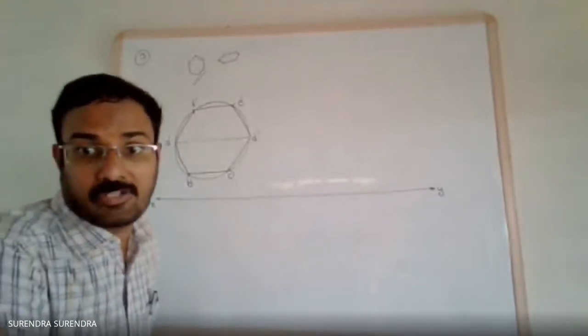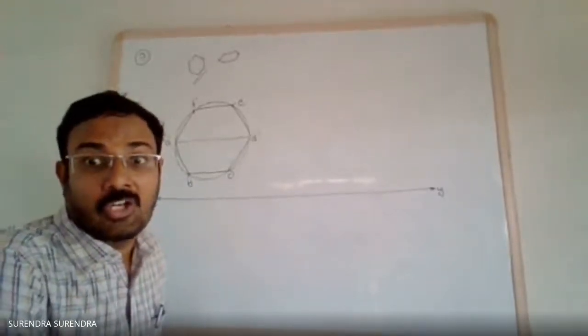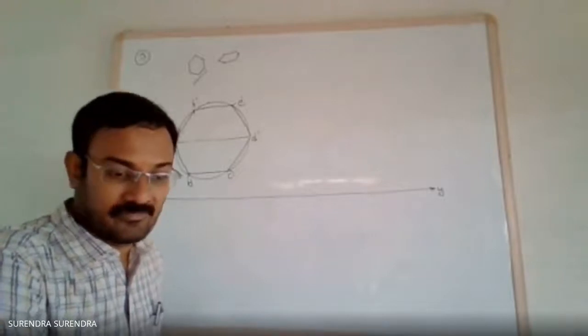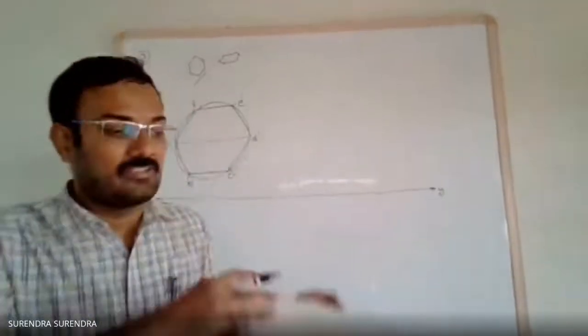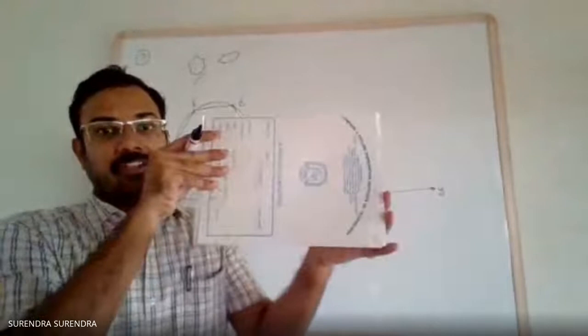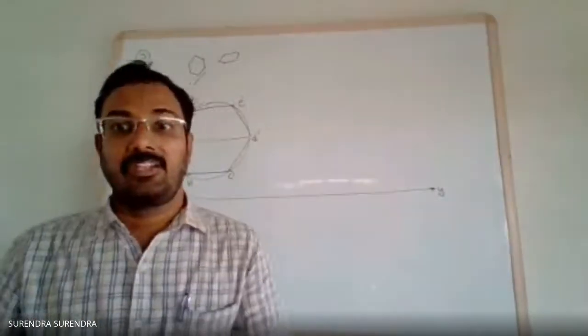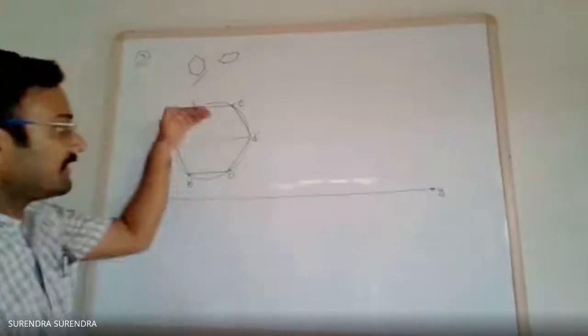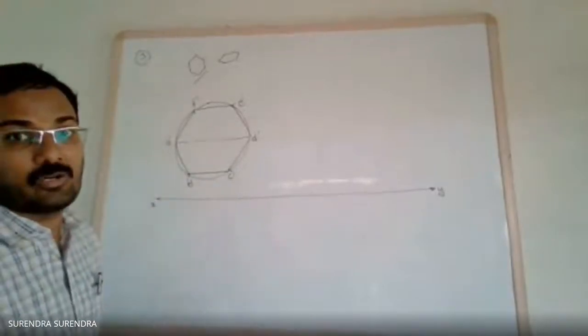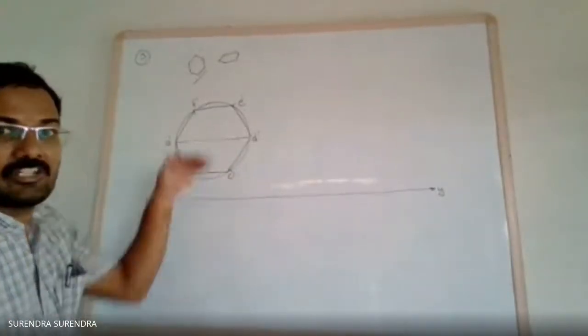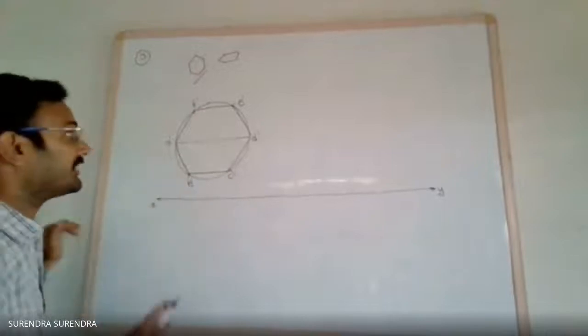When drawing the front view, it is given that a corner is in the VP. Corner in VP means initially we are assuming it as parallel at the same time. In the VP condition, its respective top view must be on the XY line. Its respective top view must be on the XY line.